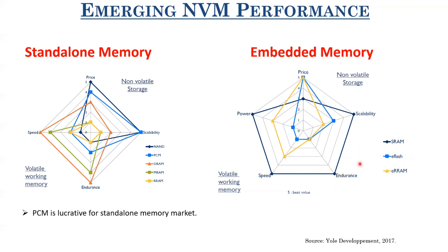Now let us talk about the embedded flash memory, which is basically embedded NOR flash memory. In terms of scalability, it's not scaling as your logic technologies are scaling. For instance, the logic technology is now at 5 nanometer. There are products on 5 nanometers, but for embedded NOR flash, the best that I have seen so far is 14 nanometer, or most commonly 28 nanometer. I've worked with 65 nanometer and 55 nanometer NOR flash while at UCSB, but the most advanced ones that I've seen are 28 nanometer embedded NOR flash, and I guess 14 nanometer ones are also under development, but they haven't been developed.